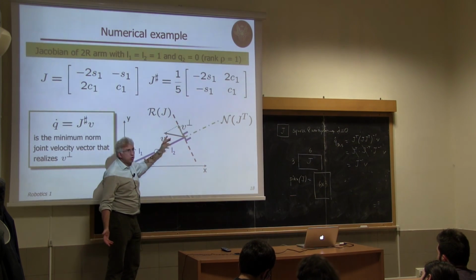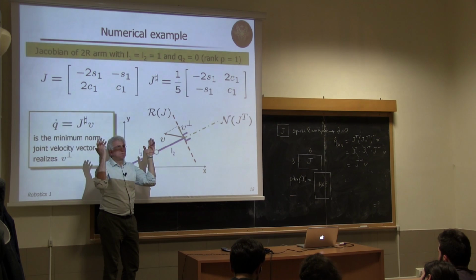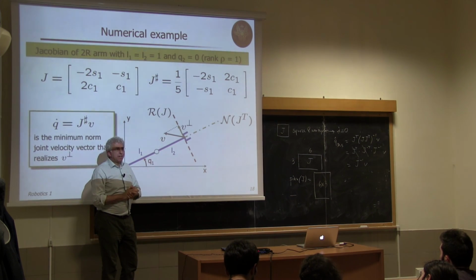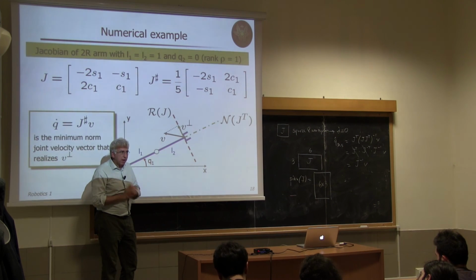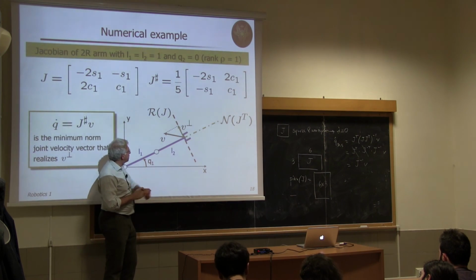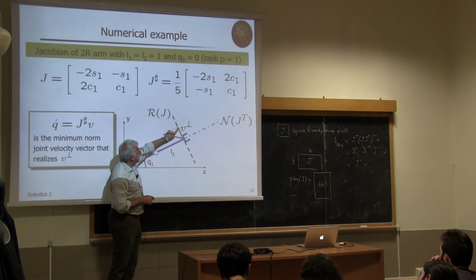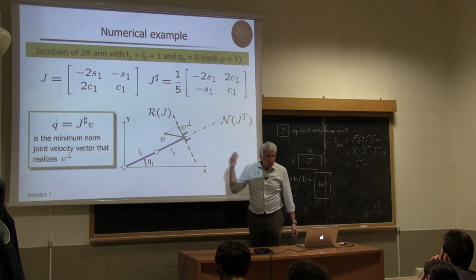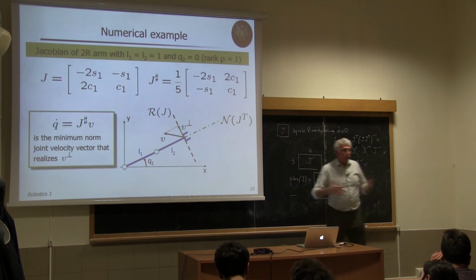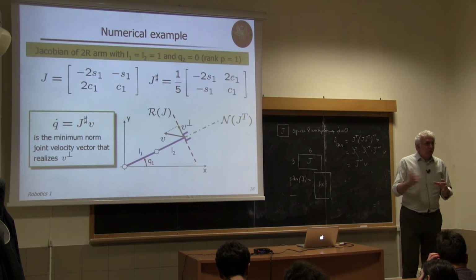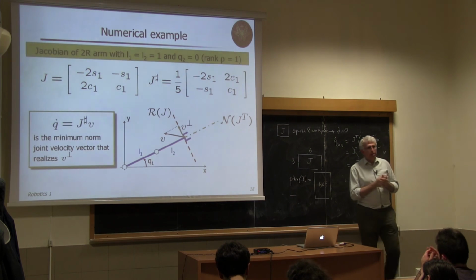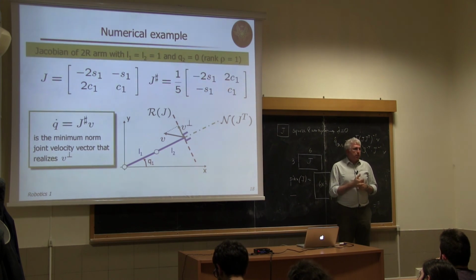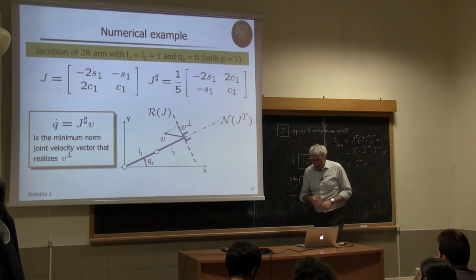If I'm trying to use J to the minus 1 here, I will get just not a number and trash in my solution, because I'm really in a singularity. When I'm using the pseudo-inverse, I will get some velocity, well, realize at least this, if not the whole V. So this is quite an advantageous solution. So the combination of pseudo-inversion and damped least square are the robust methods that are used in practice in the experiment and slowly also in the industry as a systematic way of handling these singularities.